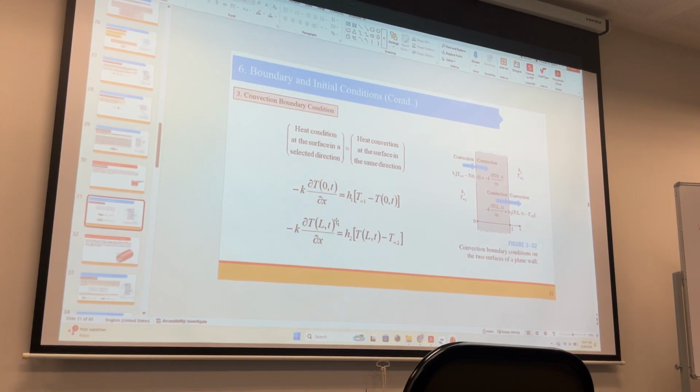It means no energy is lost. Okay, in between. Whatever is coming from the convection is going to transfer by conduction. There is no loss of the energy. Alright. Like in here, the convection will happen from here to here, from the air, right? And conduction will happen inside this wall because it's solid, right? So convection equals conduction. There is no energy lost on the surface of the wall or anywhere. Whatever heat is coming from convection is equal to conduction.